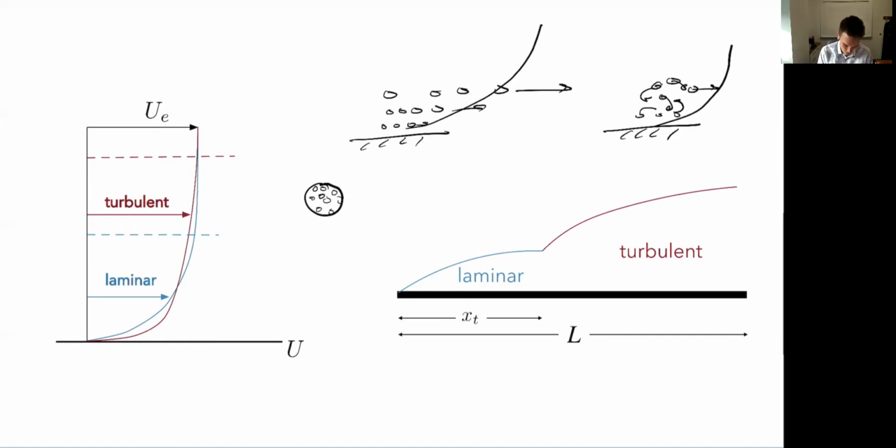The reason is that, as we talked about in the previous class, fluid is going to come around and separate and create this wake. A turbulent boundary layer, as we're seeing here, actually carries more momentum close to the wall because of all that energy exchange. So it can traverse further along the cylinder before it separates, which means my wake is smaller and I have less pressure drag.